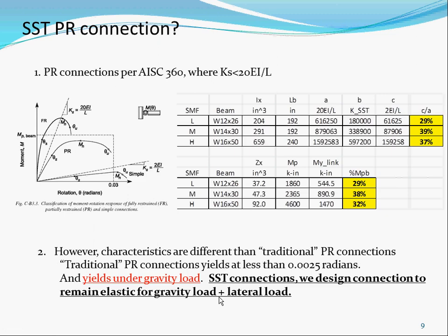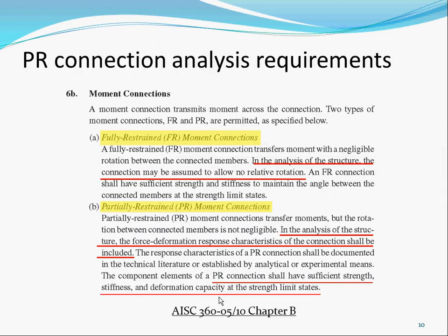We're gonna do all the load combinations, and then earthquake plus dead plus live. We're gonna come up with a moment. That's the demand, and then we're gonna size the link for that demand. Which means we're gonna be in the elastic range. So we don't yield under those loads. We only yield under like a big earthquake. But remember, we're talking about all the designs in the U.S. are pretty much in the elastic range. So that's the same concept we're gonna take when we do a design later. But this is just a background of what we are.